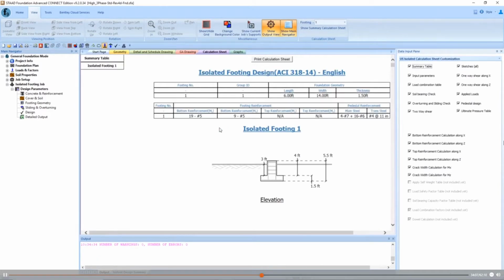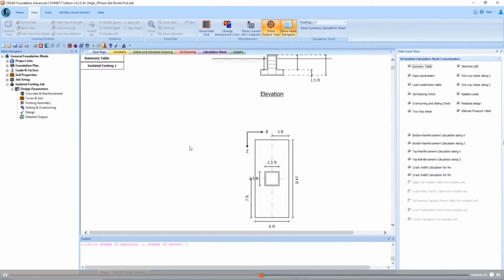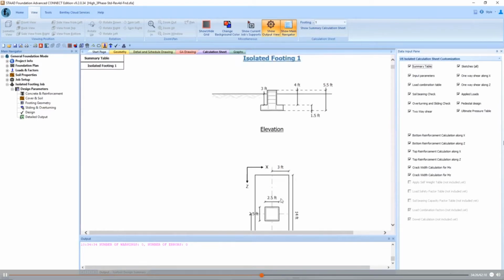Before, we had a square foundation. If you look at our foundation now, at each column line, it's rectangular. We started with a minimum dimension for the width as 4 feet and a minimum dimension for this direction as 12, and so this is what the foundation optimized to be.